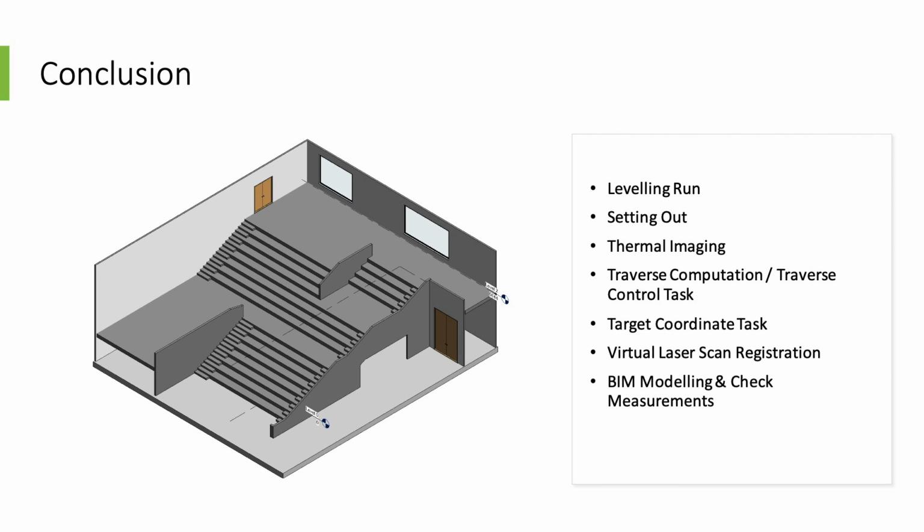The thermal insulation results appear pleasing overall, as the temperature of the surfaces of the wall was similar to the indoor temperature. The electrical sockets, however, could be considered for replacement with ones with better insulation performance. The forward bearings were calculated in the virtual traverse task for each of the stations using the given virtual sheets, leading to computing the coordinates. After doing so, these were plotted to compare their positions to the original control network. These were proven to be computed right.